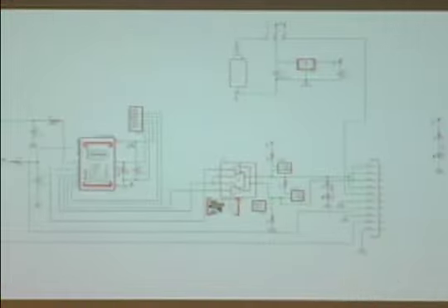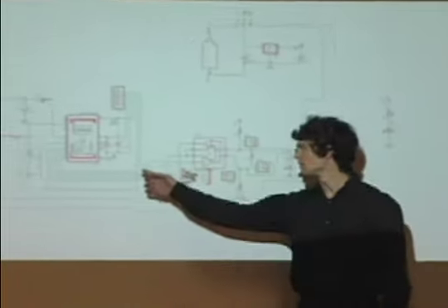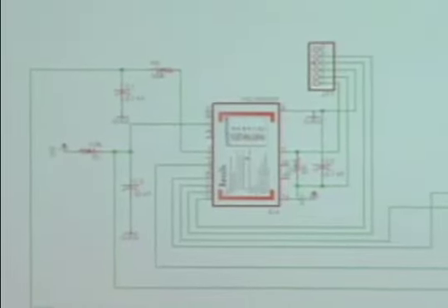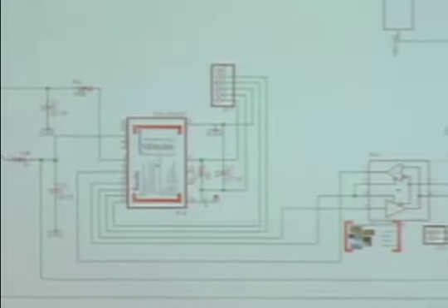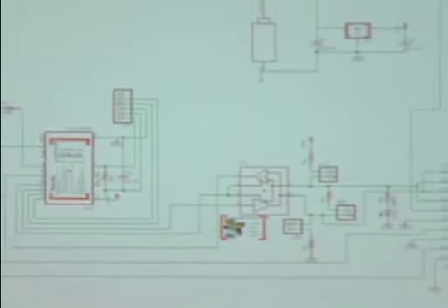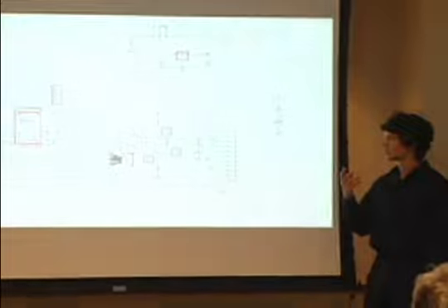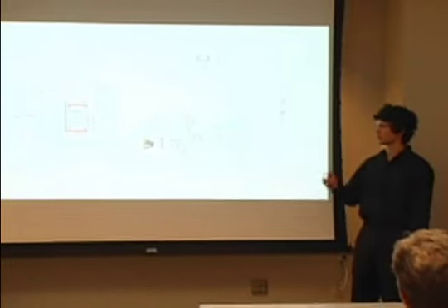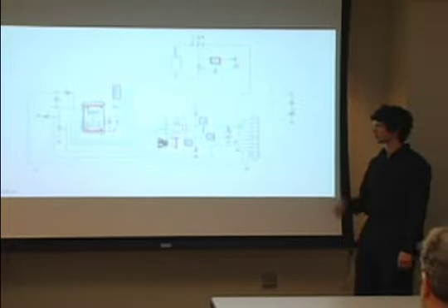So here's an overview of our circuit for our pygmy meter instrument. Over here is our PIC microcontroller, which takes in readings from the pygmy meter itself. Since it closes a switch, we have the switch between our input pin and ground, so it is a normally high pin using a pull-up resistor.